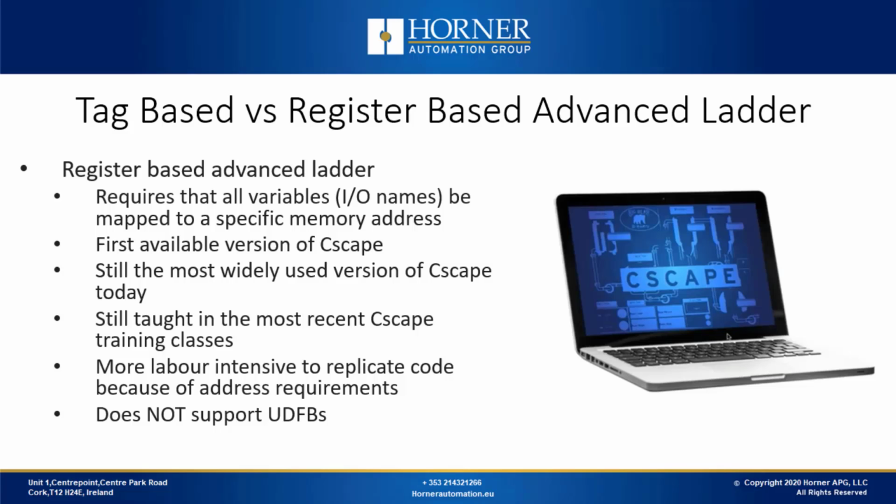However, there are some downsides to using register-based logic. It is the most labor-intensive when it comes to replicating code, because of the addressing requirements. So if you have a section of code that you want to replicate, for example, code for a pump, if you have several you want to use, you can easily replicate the logic, but you have to manually readdress the newly replicated code. Also, for similar reasons like the addressing, register-based logic does not support user-defined function blocks. User-defined function blocks are very powerful tools that allow you to efficiently reuse sections of your code.